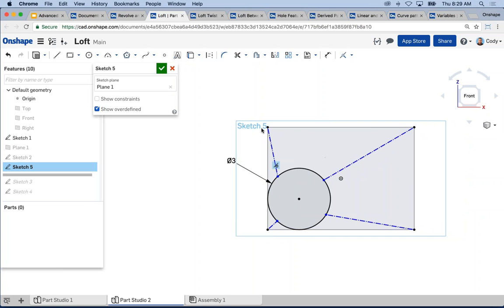But once I'm satisfied with the locations, these lines give me useful references to split the circle. And that's ultimately the goal. By splitting the circle, I create 4 vertices on it, and those vertices can line up with those points on the rectangle when I go to do my loft, right?